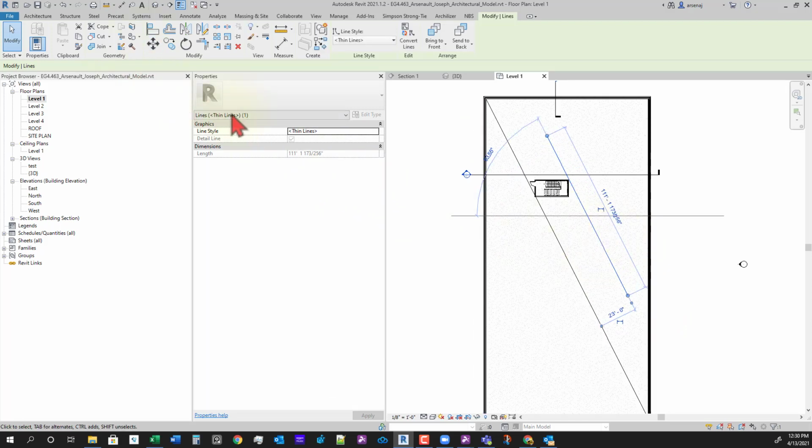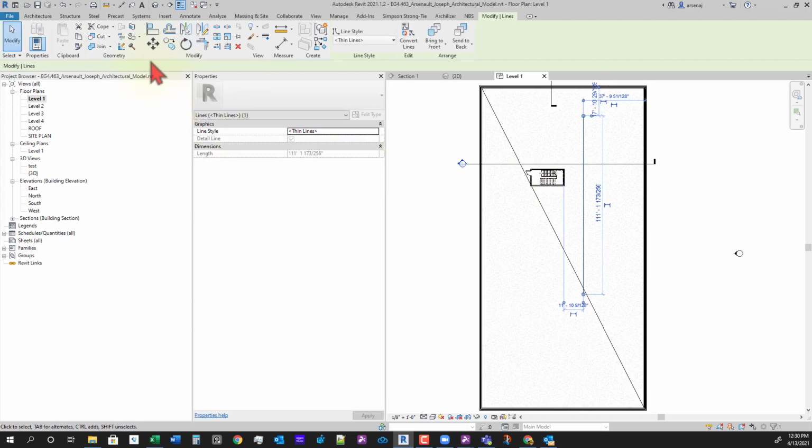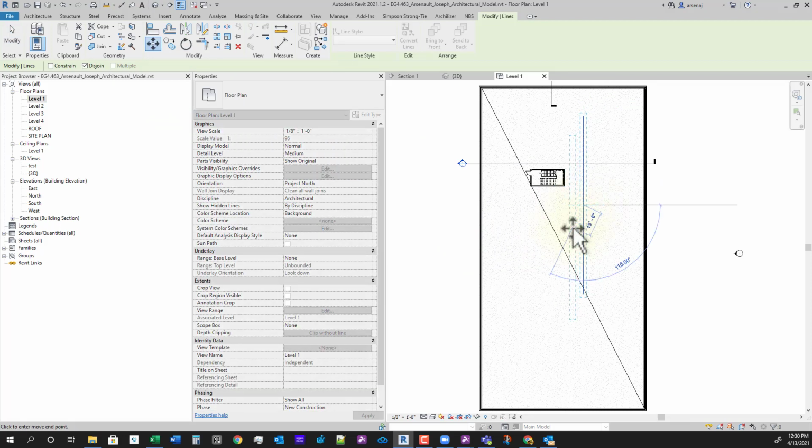Next thing we'll want to do is rotate. If we go up to the Modify tab, you can hit Rotate. It selects the middle of the line, or the middle of the geometry, whatever it would be, and then you can move it clockwise until it'll snap at 90 degrees. And we can hit Move again, grabbing that midpoint again, and then picking the midpoint of our diagonal line. Again, if you're having trouble getting the midpoint, type SM, and that's the snap mid